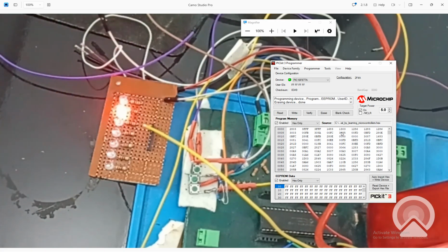See, it's even faster. So guys, in this way you can use timer 0 for generating delays in a PIC microcontroller, and this has a lot of benefits because you have the timer flag here. You can do a lot of things with this.